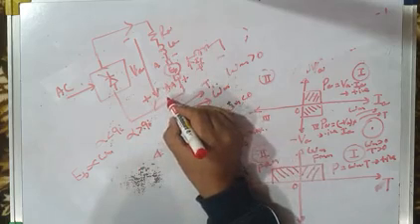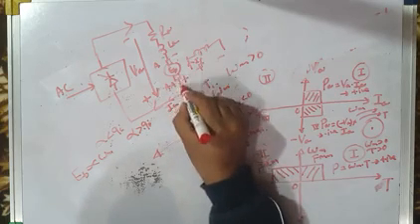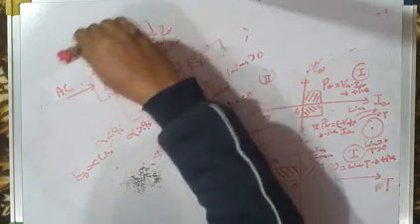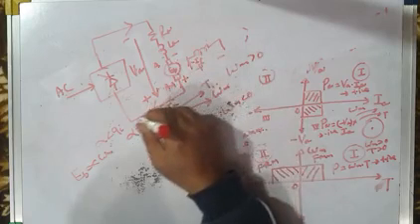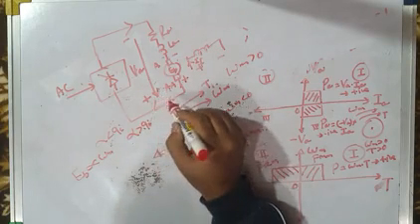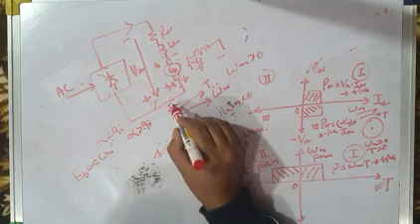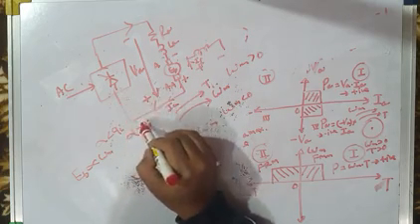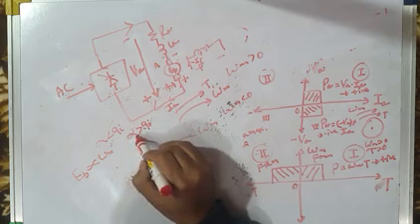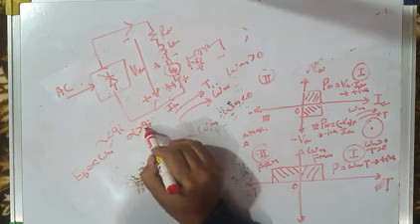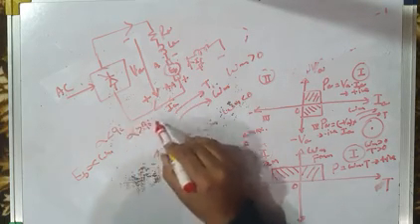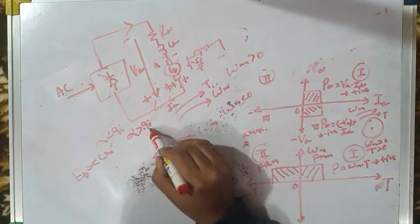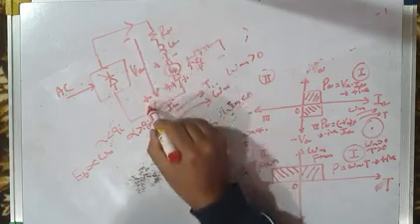So, the current is now coming out from EB, and it is flowing, of course, in the same direction. But earlier it was flowing from VA to EB. Now it is coming from EB and flowing towards VA. And you have to limit the magnitude of the current. In order to limit the magnitude of the current, you have to operate your converter in the inversion mode. And we know that the converter operates in the inversion mode for alpha greater than 90 degrees. In the motoring mode, alpha was less than 90 degrees. In the regeneration mode, now alpha has to be greater than 90 degrees